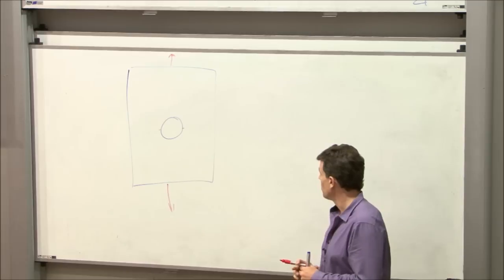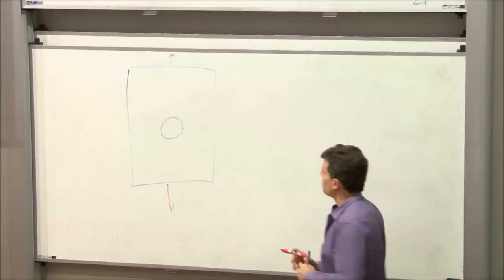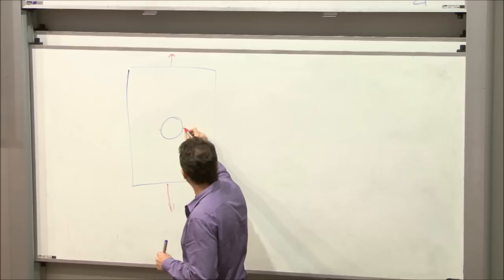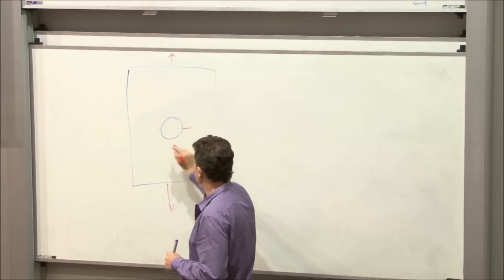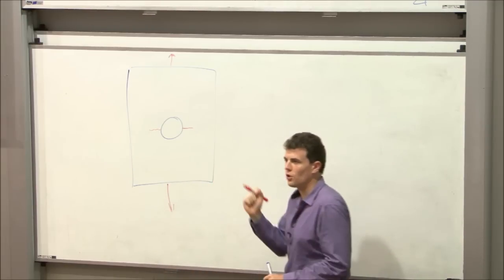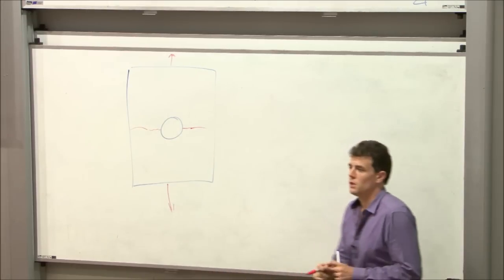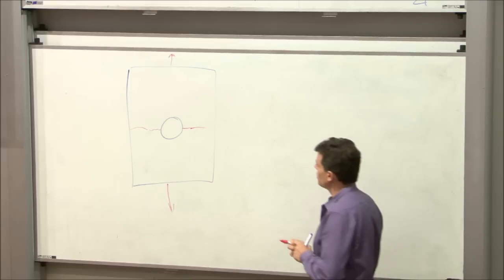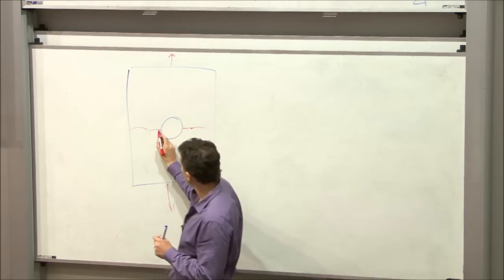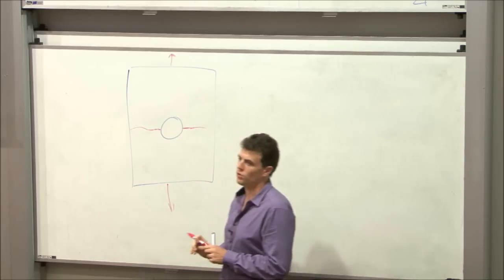Now, those little cracks don't necessarily mean that the part will break into two pieces, but if they get big enough, not necessarily all the way to the edge, all of a sudden when the part's loaded, it will just split into two pieces. So we need to have an understanding of how these cracks grow and how long they take to grow.